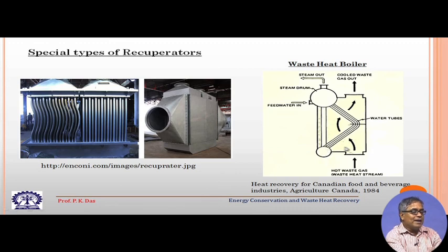To increase the contact time between the hot gas and the riser tubes, we have bent tubes. You can see that there are a number of riser tubes, but only one downcomer tube, though the mass flow rate is the same for the entire circuit. Here we increase the surface area, because we need heat transfer. By bending the tube, we increase the contact time between the hot gas and the fluid flowing through these tubes, and then the waste gas comes out.